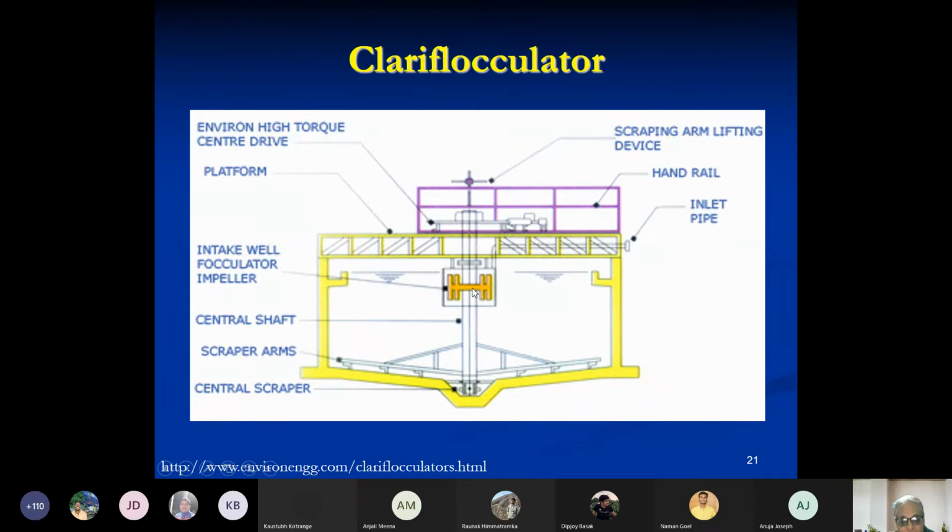So the velocity of the water here is maximum, and as you go further away to the edge of the tank, to the periphery of the tank, you will get less velocity, but that's not what we are interested in. We want the particles in the water to start settling. Okay, so in this whole thing, they have to start settling.